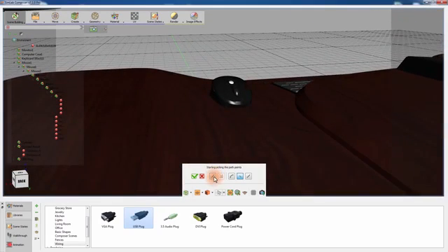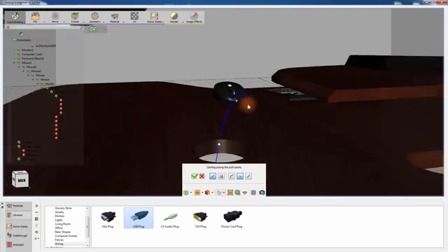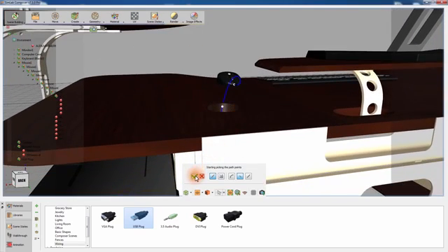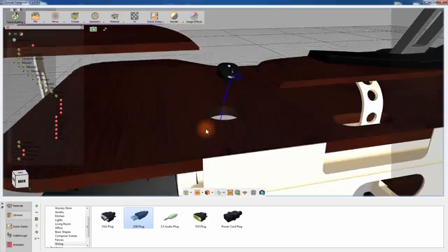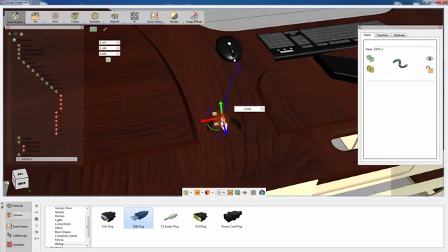Enable the Apply Tangent while picking option again and click on the front of the mouse. Click on the green mark to finish the path creation process. You can click on the path's hard points after the creation to control the location of those points, which in turn control the shape of the path.